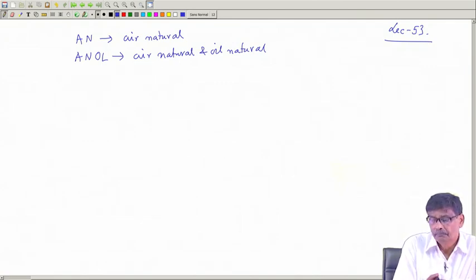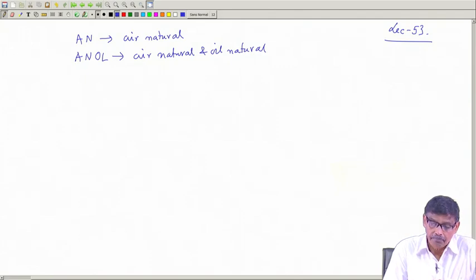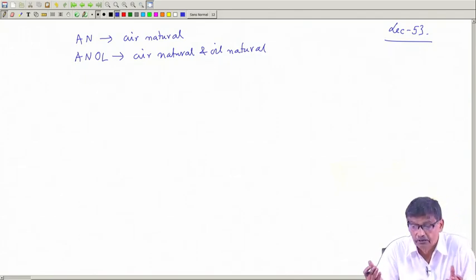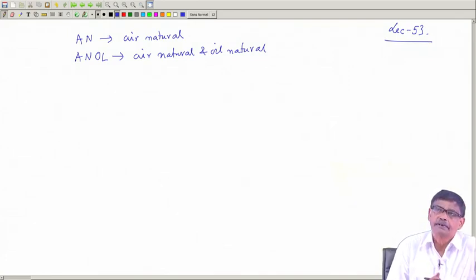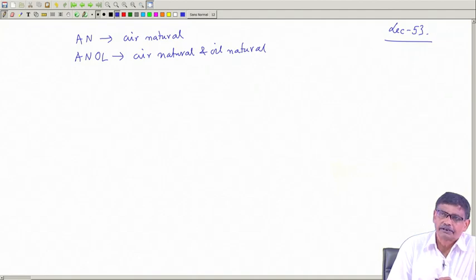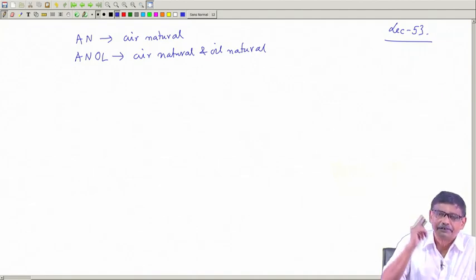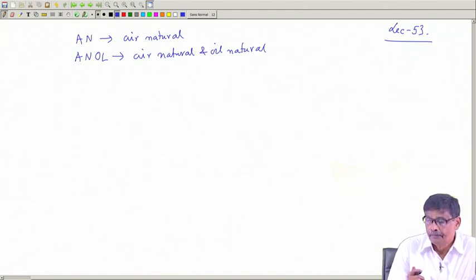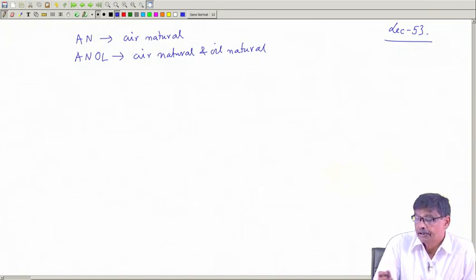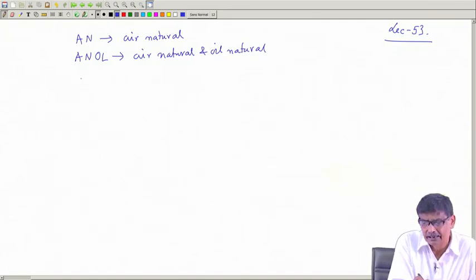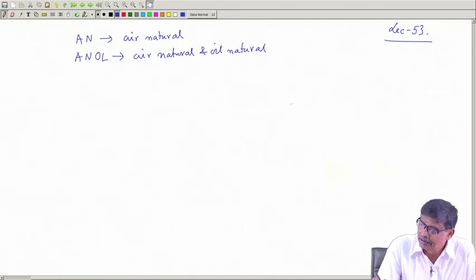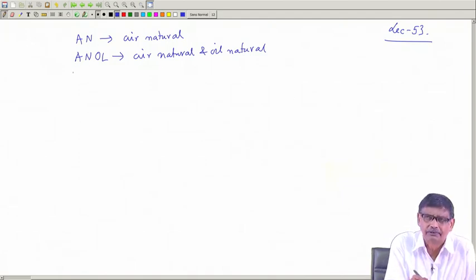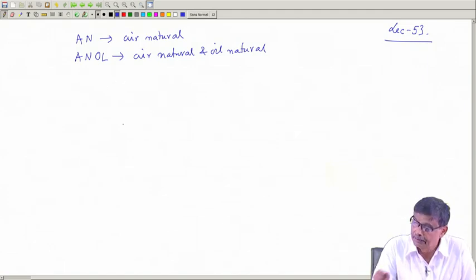Now, there may be very big transformers. Then cooling tubes is also not sufficient. For example, transformers of ratings of 100 MVA, which are used in power stations. Very large transformers, 3-phase. In that case, you will find there are several like oil forced, air natural, this kind of thing, but you go through books, you can easily make out what do they mean.